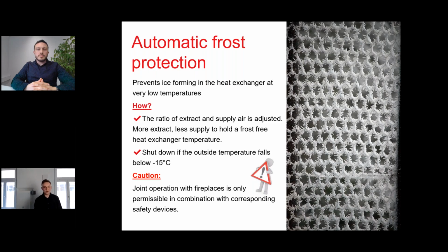But take care with a joint operation with fireplaces. This could get very dangerous. I need to say that the joint operation is only allowed in combination with corresponding safety devices in compliance with regional regulations and standards, because it could happen in frost protection mode that an under pressure in the apartment is produced because we are going into an unbalanced mode.